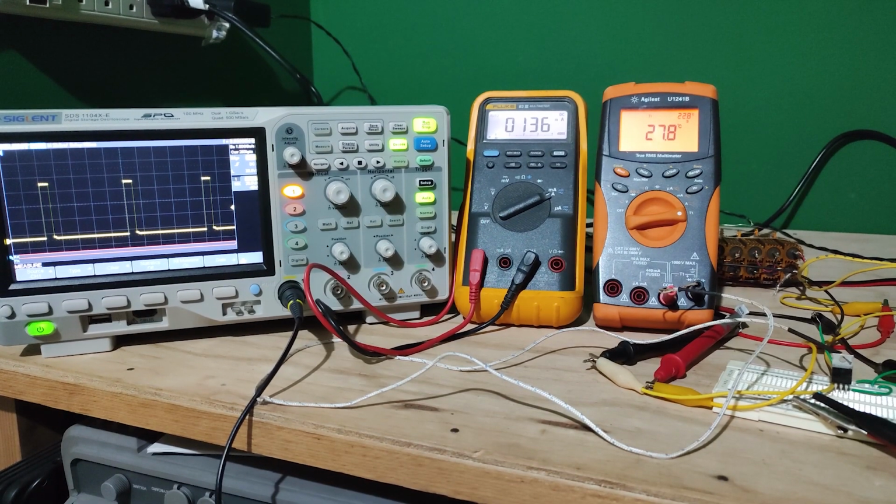Okay, for this first test, we have the PWM control. We have the PWM signal to the left and the multimeters to the right to show the current flowing through the transistor and the temperature of the transistor. We are going to change the duty cycle and we are going to see that even though the current flowing through the transistor changes, the temperature will stay relatively the same, within 10 degrees of change at most.